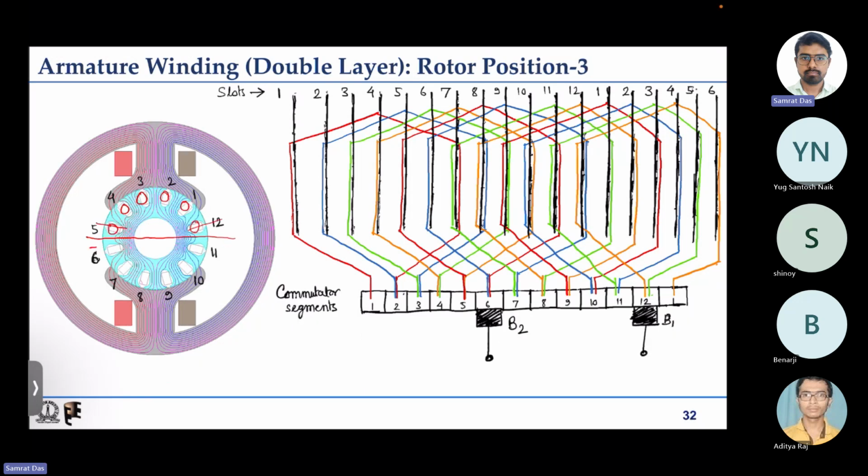And in this case, four coils have non-zero induced EMF, again 10 volt per coil, so we have 40 volt. We understood last class that if we have more slots, then this small ripple between 40 volt and 30 volt in the induced EMF could be reduced, and made negligibly small if the DC machine is designed well, taking care of all these things.